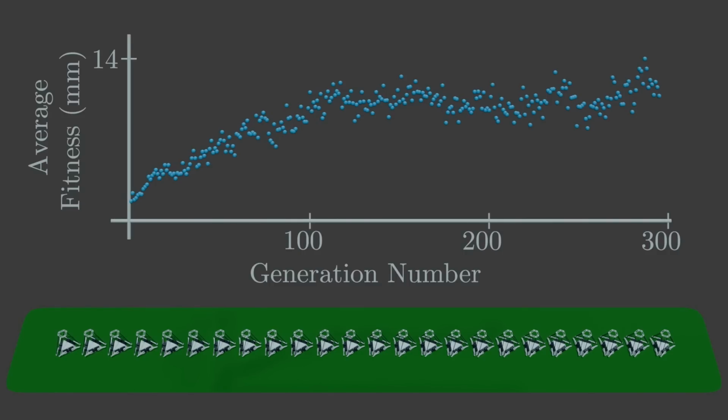Before restarting the algorithm, I decided to remove the genes for the periods of the sine waves, and set a uniform period across all the degrees of freedom for each robot. I did this because in the previous algorithm, the different degrees of freedom weren't syncing their movements up well. Removing them cuts out interesting solutions that may have been found, but I think this is the best method for finding better solutions now.